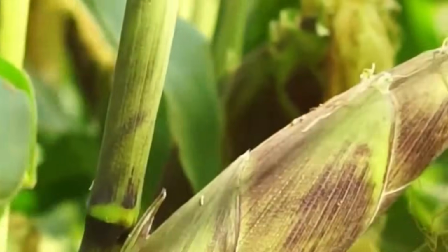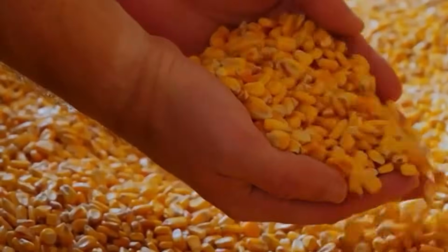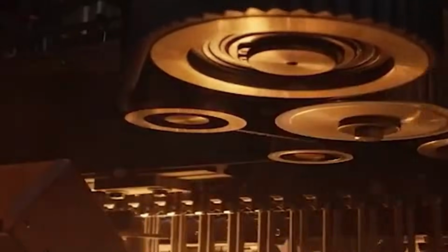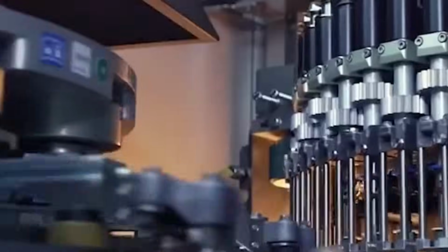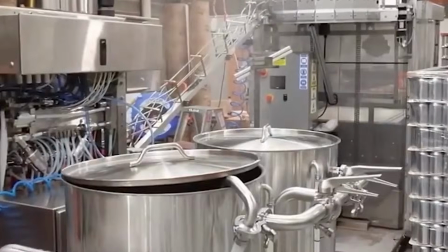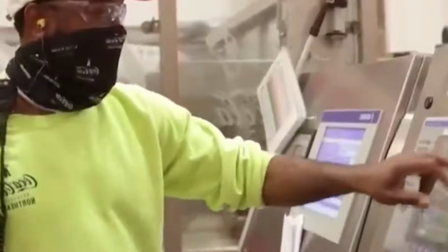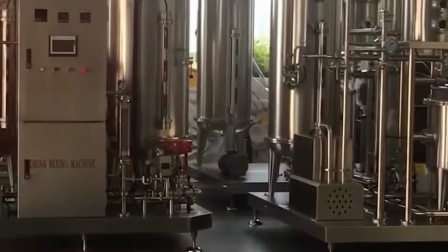The carbonated beverage is delivered from the pressurized buffer tank to the filler bowl. Each container is raised into position and sealed against a filling nozzle. First, the internal pressure of the container is equalized using a pre-evacuation chamber. Then, the valve opens and liquid flows in under gravity or slight overpressure.